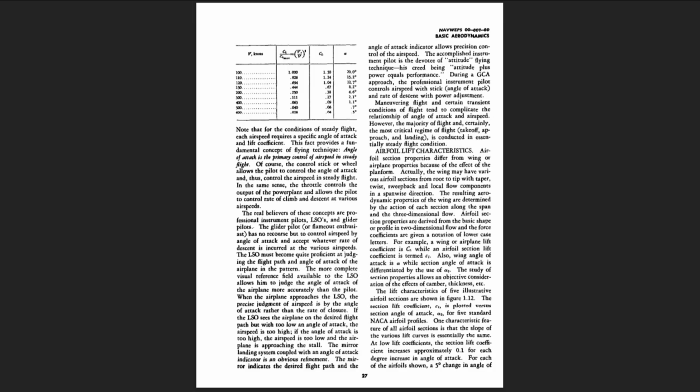CL max equals 1.5. Vs equals 100 knots EAS. Note that for the conditions of steady flight, each airspeed requires a specific angle of attack and lift coefficient. This fact provides a fundamental concept of flying technique. Angle of attack is the primary control of airspeed in steady flight.